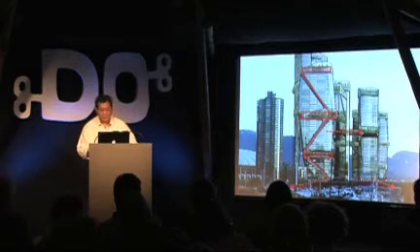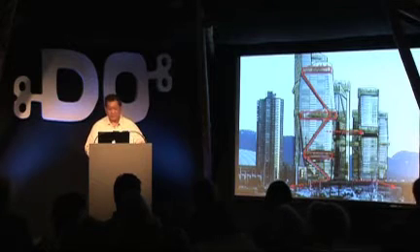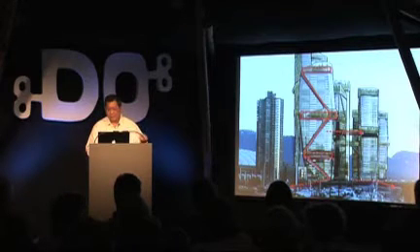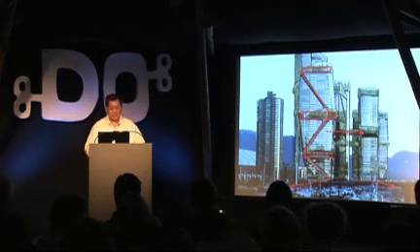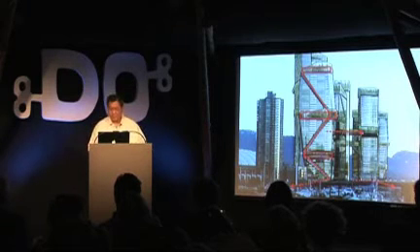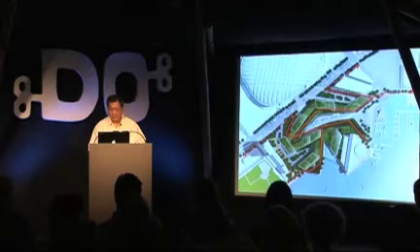So here we have the vegetation that starts from the ground, works its way up diagonally, and then at the bottom, one third of the way up, and two thirds and three thirds, we would have green sky courts, and then over that we would have green bridges. So the linkage is not just at the ground plane, but also at the upper parts of the building. And we were able to achieve about 30% equivalent of the built-up space in greenery, both on the facades and in the sky courts. This is the plan of the project, and you can see this is the green infrastructure.